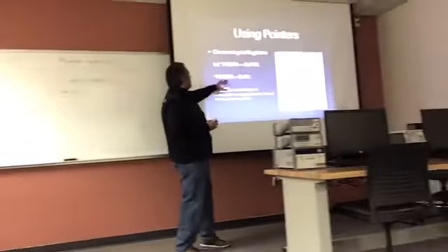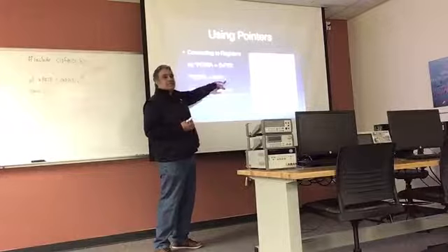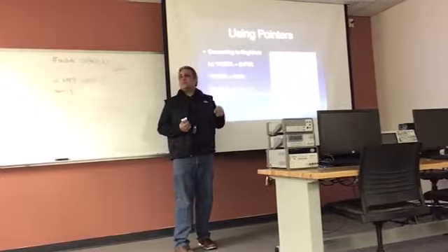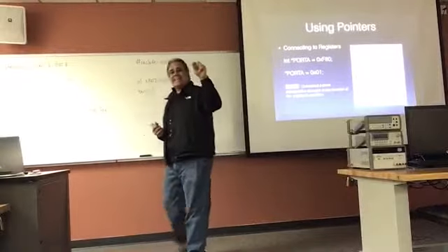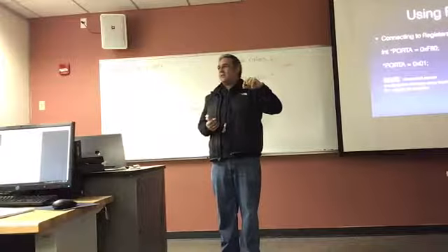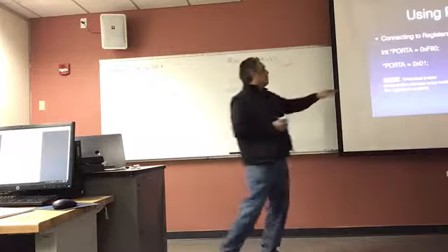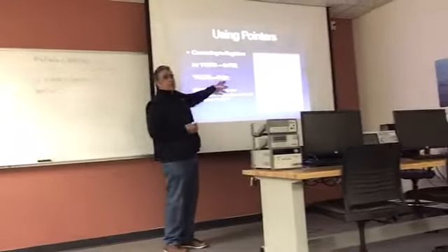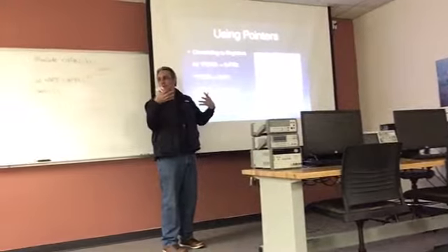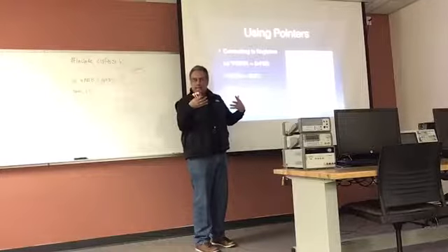Every time I use the pointer, there is only 8 bits associated with it because my microprocessor is an 8-bit device. If my microprocessor was a 16-bit device, then every time you use the pointer, you're going to connect a 16-bit number to it. You see that?